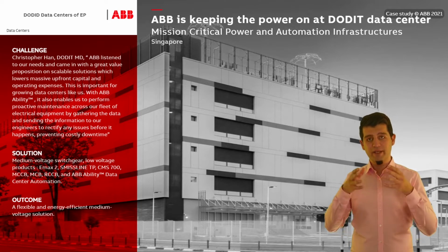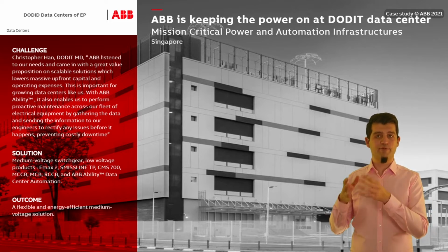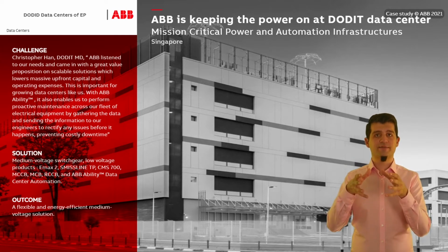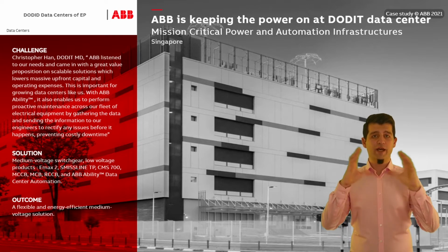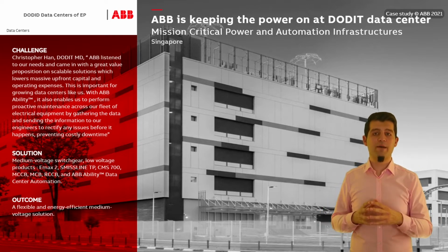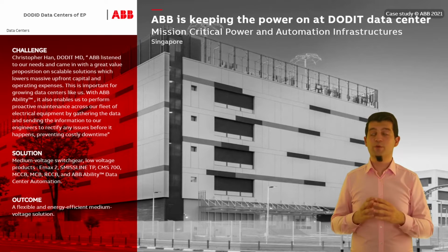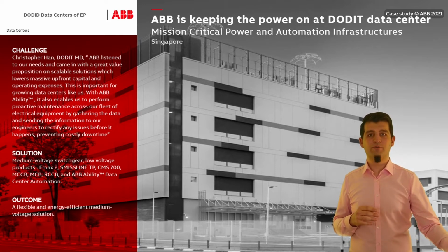And specifically, our portion from the sub-distribution side was building the components XT4, XT5, S800s, CMS, S200s, current transformers, all of that into third-party tap-off boxes into busbar systems. So that's what we did successfully with NextDC, also a very huge project for us.